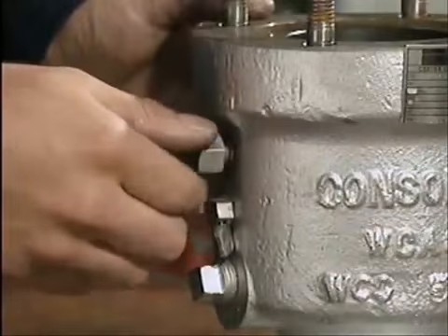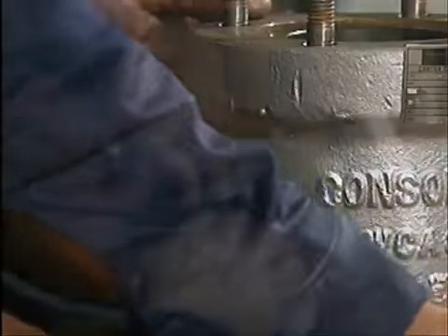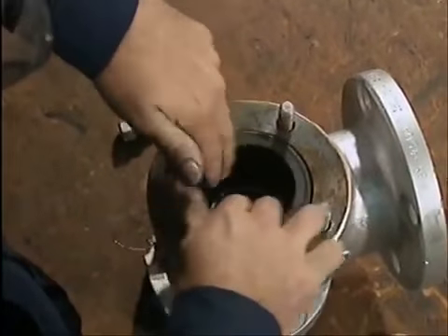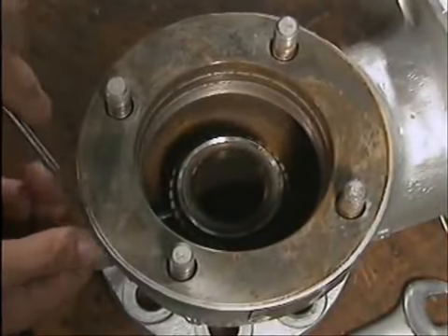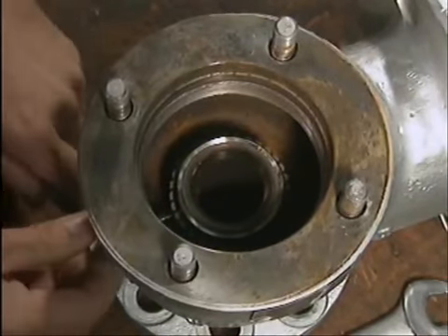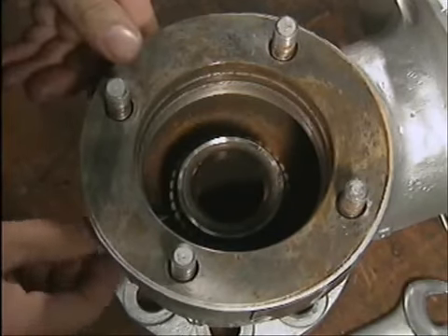The locking pins fit into notches in the upper and lower adjusting rings. Break the upper locking pin free and remove it from the valve body. Then unscrew the upper adjusting ring and set it aside. Now repeat these steps to remove the locking pin for the lower adjusting ring and measure the exact position of the ring.